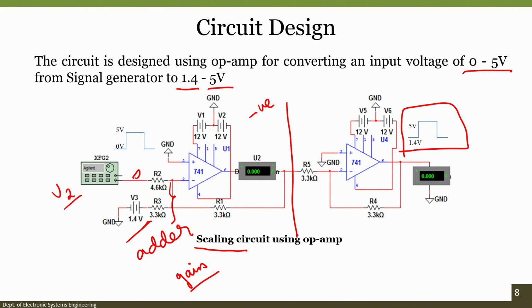So, this was the discussion about how you go about designing a signal conditioning system for an MQ7 gas sensor. Let us get hands on and rig up the entire circuit and see how we can implement this in real time. This was about the signal conditioning part, how you can design the scaling system and get the desired voltage, provided you have a constant analog function generator where the input cannot be altered to the desired range. It is just a 0 to 5 volt constant range.